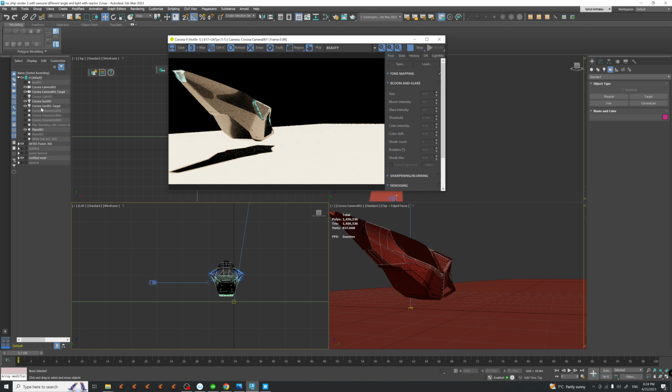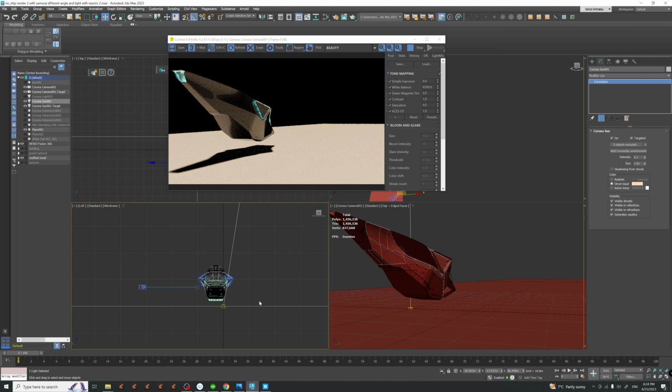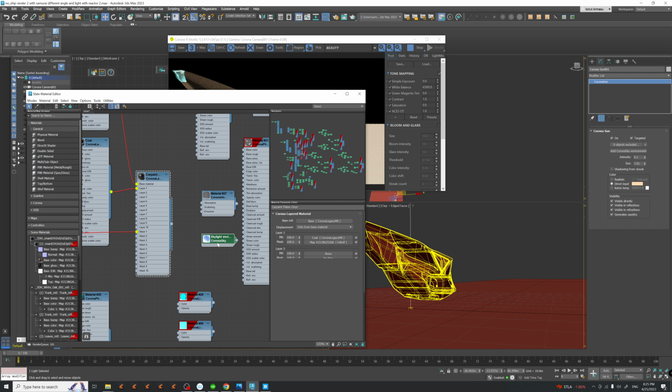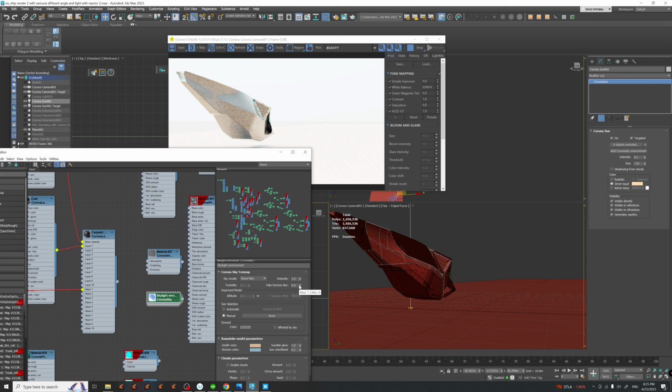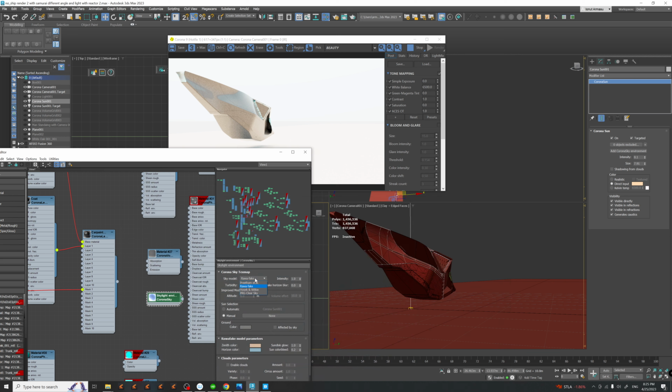Okay, quite exposed. I don't like to use the exposure and all that kind of stuff, especially in the beginning, because once we add the fog and more other details, I prefer to adjust them around instead of relying on simple exposure. Now we don't have any skylight environment, I suppose, yet showing around. There you go. So we have the skylight environment now at 1 as intensity. It's quite a lot, but it may help us in the long term because our foreground background is quite white.